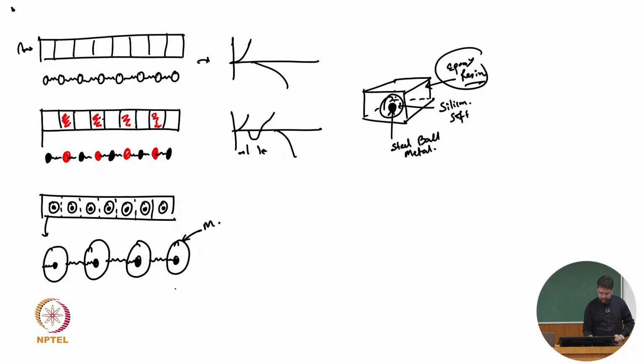So these are the mass M, these are the small mass mr, these are kr, and these are K. That way we can get that. Now if we think how the equation of motion of that full thing comes, we are lumping that mass. Let's say this is my nth cell, and I assume that the inner mass displacement is Vn and the outer mass is Un.